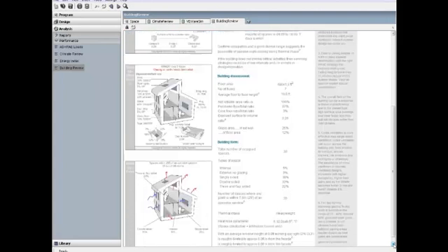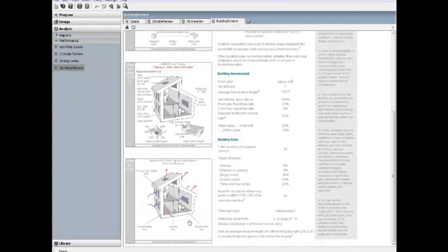The building form section points to another complex calculation, the number of spaces within 25 feet of a window. This calculation reflects the amount of natural and cross ventilation that's available in the building and is applicable to LEED credits. Research has found that up to 20% of heating or cooling loads can be saved by moving rooms around.